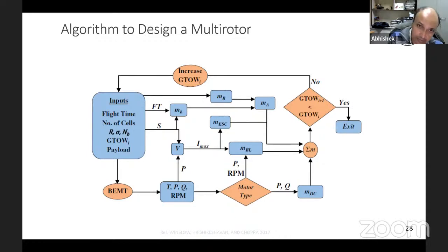That's where you have to apply a thumb rule, which is the convention. Even when people were designing an eVTOL vehicle like Vahana, which was done by Airbus, they used the same idea. So in my multi-rotor case, where I require 250 grams of thrust, I will select a motor which is capable of delivering 500 grams of thrust. So it has the power capacity to handle double what I require in normal hovering flight.